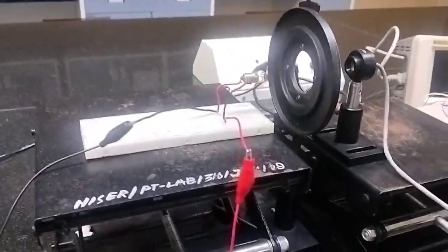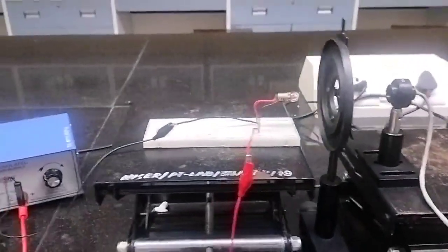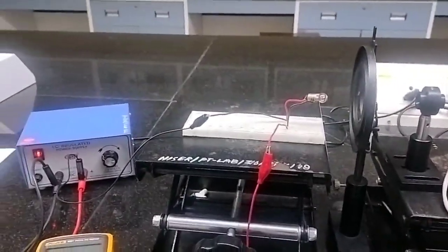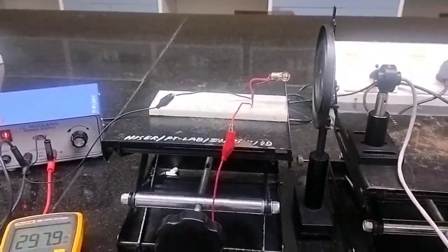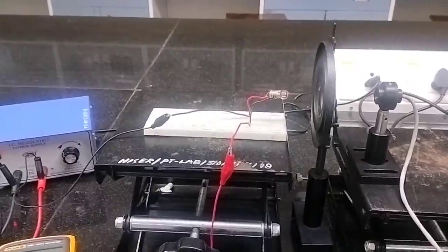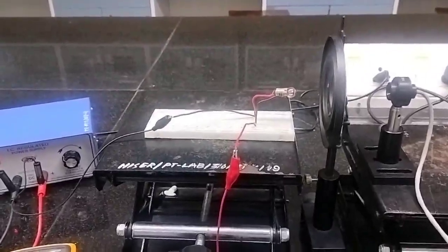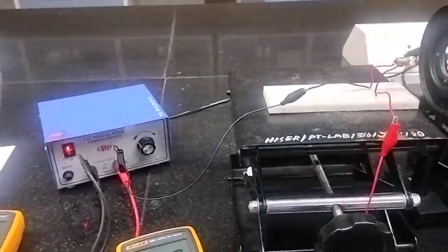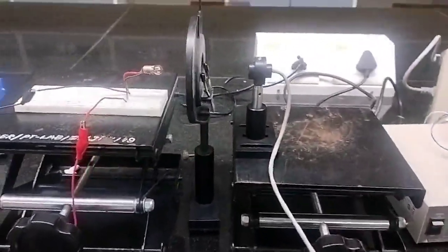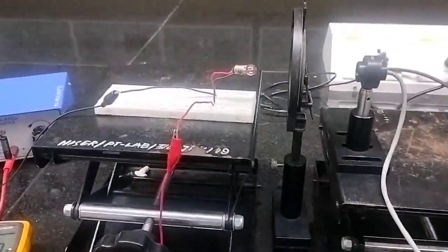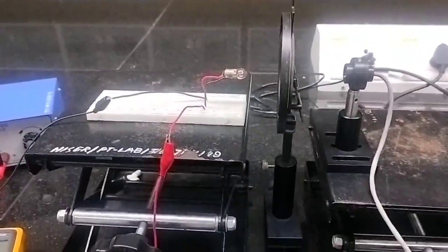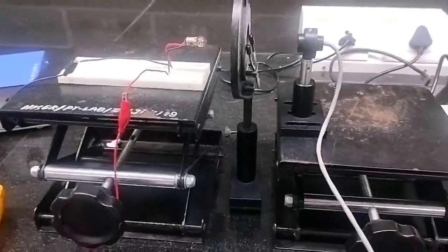The three important characteristics are: the first one is the spectral response, that is the relationship between photocathode sensitivity and wavelength of incident light. Then we will study current gain, meaning the ratio of anode output current to the photoelectric current produced at the photocathode. And the last one is the dark current. That means when no light is incident on the photocathode, a small current is observed at the anode, and that is the dark current, which we are going to measure.